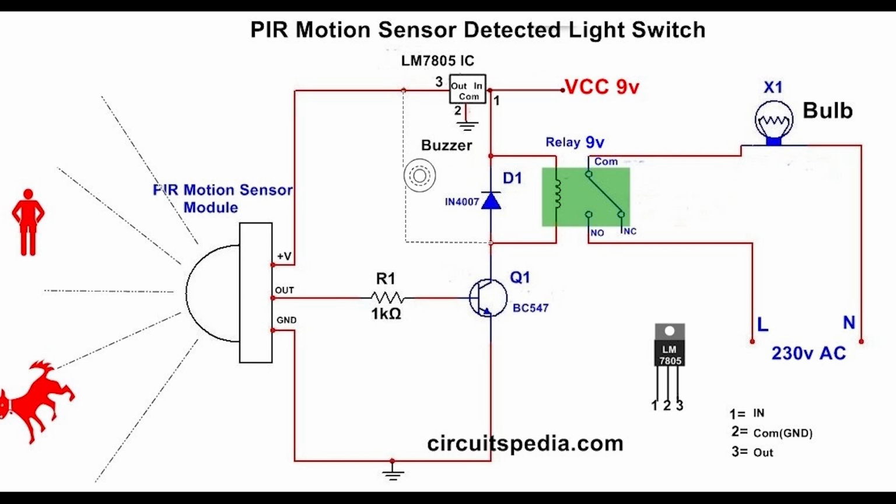As an object moves from one zone to another, the IR radiation detected by the sensor fluctuates. The fluctuation results in a change in the electric signal generated by the pyroelectric material. These signal outputs are actually very small, so they require amplification. The amplification is usually done by the BISS0001 IC. That is a very new IC to me. Using that circuit, or additional circuits, very simple circuits for the module, as this